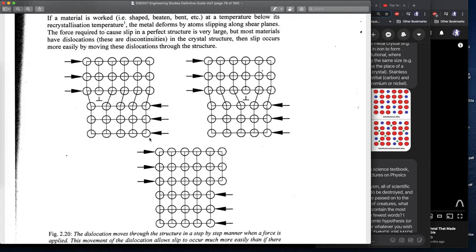You guys familiar with this? Does that make sense? Intuitively? Yep. Okay. The next thing is, we know that when we bend those coat hangers back and forth and back and forth, suddenly they break. Again, is that something you're familiar with? Yep. Okay, so we have that intuition. So there's an idea that the first time we bend it, we're actually making that steel stronger. And we're making it stronger because we're moving those bubbles away, or we'll get to that later, what we're actually doing is we're making it harder for it to move those bubbles around. Let's just move that for the moment.